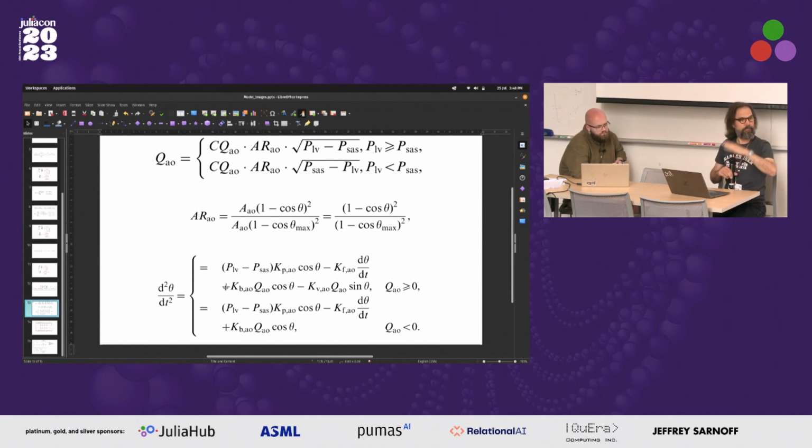And we have friction, which has d theta dt in there, which is the velocity. So that's the friction term. And we have that kV is a coefficient for the pressure in the wake behind the leaflet. So that's the three driving force parameters, driving and damping force parameters that drive the kinematics of that valve.